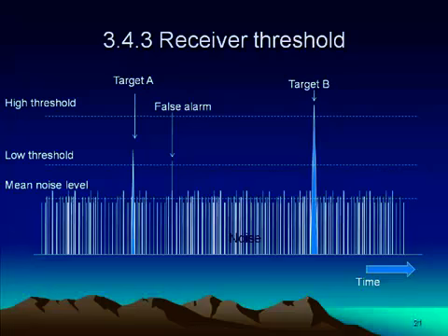If you keep a low threshold, then due to the echo signals from the targets, definitely you are going to get a proper indication. But at times, the noise present may be crossing the low threshold limit and it may be indicated as though there is a target present to the operator. So physically there is no target present, but the indicator is telling you that there is a target. This condition is what we call false alarm. This must be avoided at all situations.